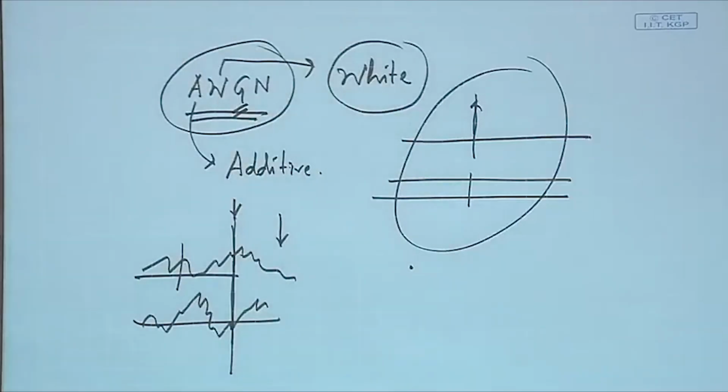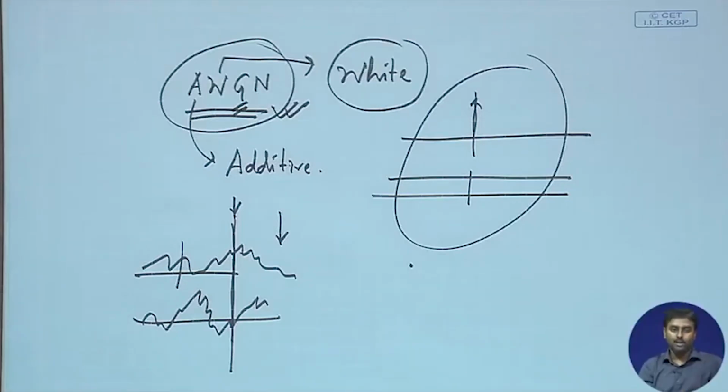That is why, whenever we talk about a particular channel and a noise process being added, we take help of additive white Gaussian noise. There are other noises for different systems; in an optical system it will probably not be similar, because of photon counting, and that counting process becomes Poisson. So different kinds of noise can also be added, but generally most receivers are analyzed with respect to additive white Gaussian noise. That is why it is very important that we know all these terms.